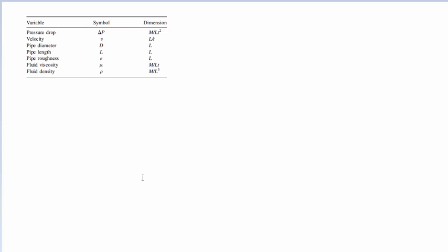They knew that these variables were the ones that mattered the most. So they did what we did in the last lecture: they tried to use the Buckingham Pi theorem. They chose velocity, inlet diameter, and density as our repeating groups, and looked at what happens for the remaining variables, just like we were doing before. The remaining variables were the pressure drop, length of the pipe, this E, which is the roughness of the pipe surface, and the viscosity.